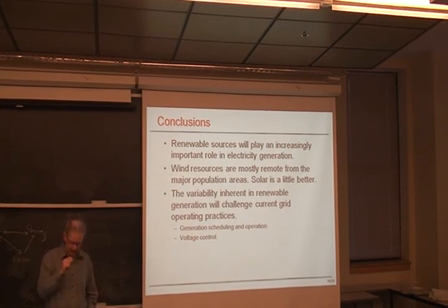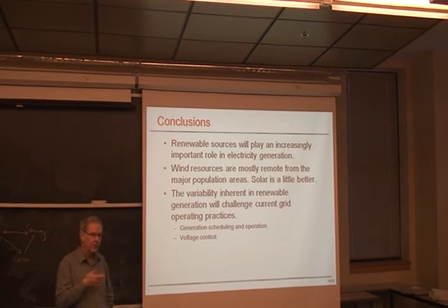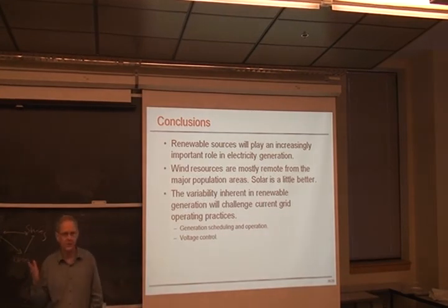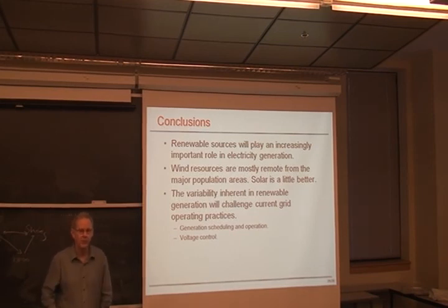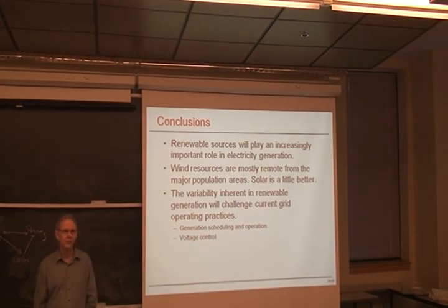That's with wind. With solar, there are no moving parts, and so typically solar is being operated at its maximum power point. There are control algorithms to do that. You can very quickly move it away from that point. There are no mechanical parts, it's all electrical. So almost instantaneously you can drop output from solar as well. But again, you can't increase. It's a one-way control mechanism.